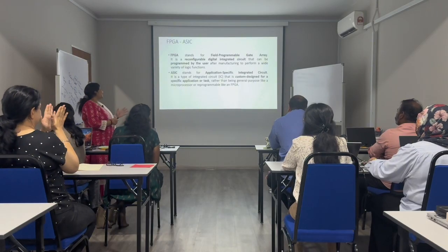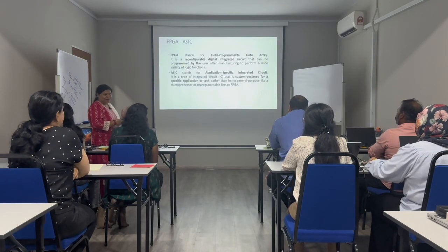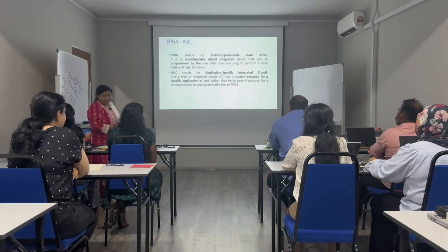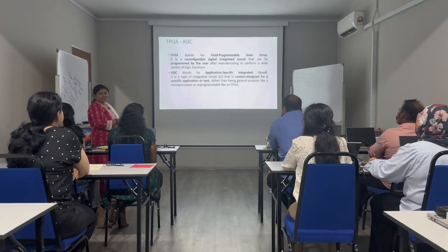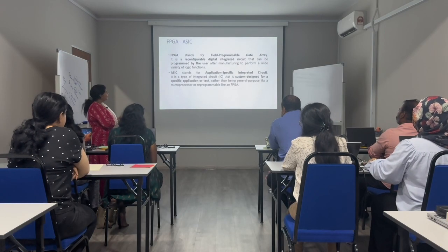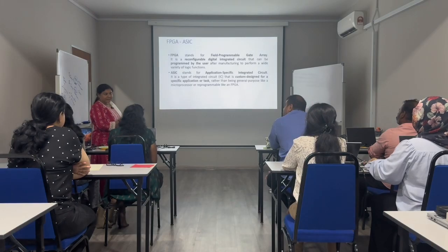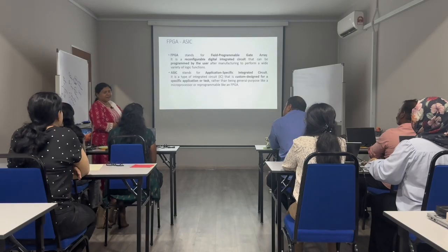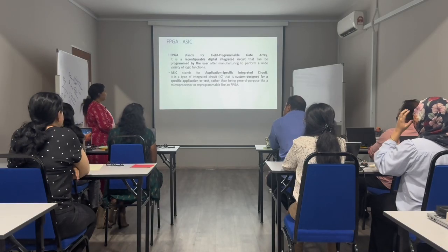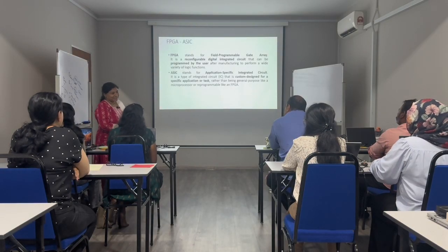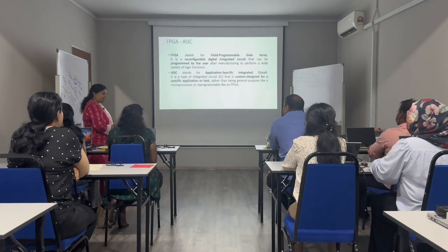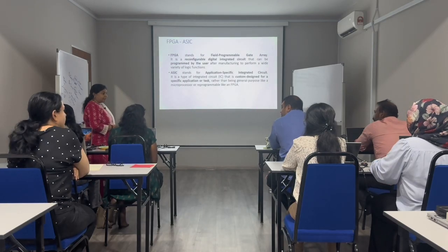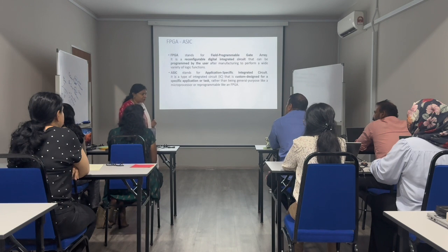Yeah, very good. So FPGAs are reprogrammable devices, and ASICs are not reprogrammable. The turnaround time for an FPGA is very minimal, maximum around 4 weeks, and for an ASIC it will take years. Turnaround is the relevance of the product, the completion of applications.